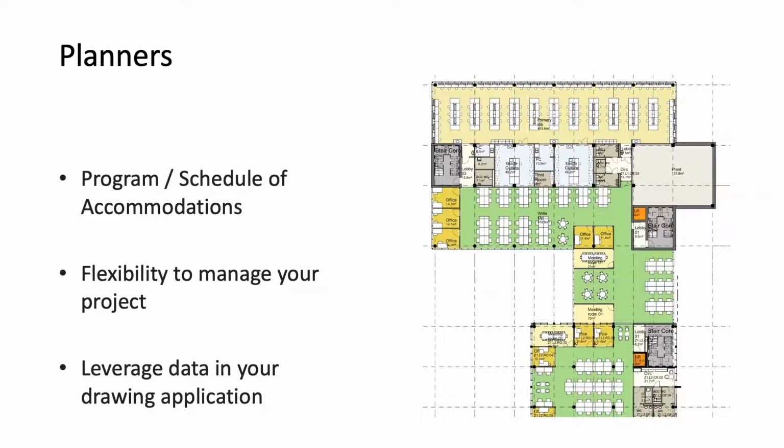Also, from an engineering perspective, we've had it where we have a room that has a lot of heavy equipment in it. So from a structural perspective, they need to reinforce the slab underneath that room. So instead of having to talk to our engineer and say, hey, you need to do this room and that room, we put it as a requirement in the room, we pushed it into dRofus, they set up a colored floor plan. If the room shows up red, they know they need to provide additional reinforcement in that room.